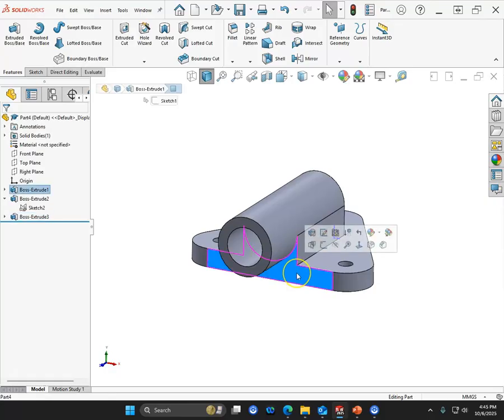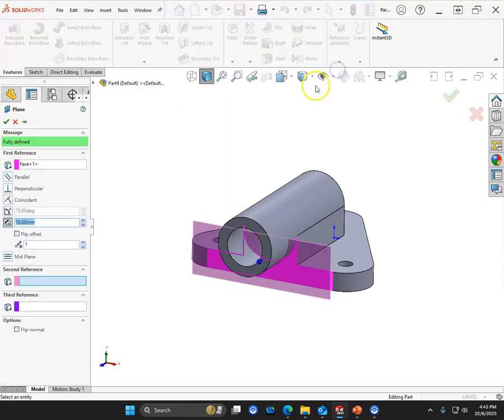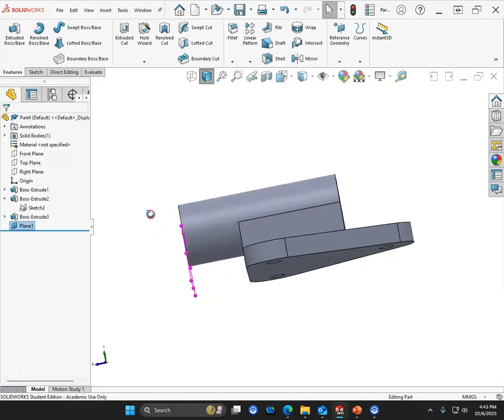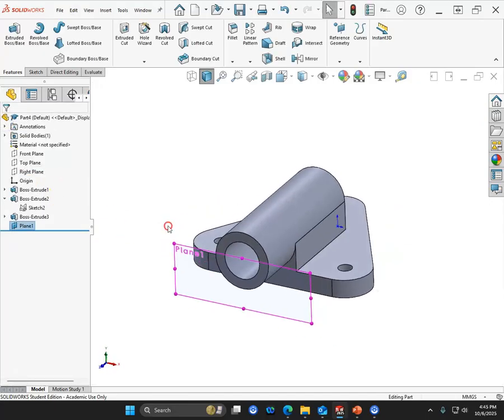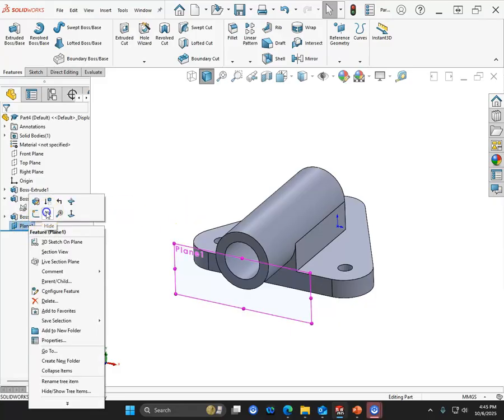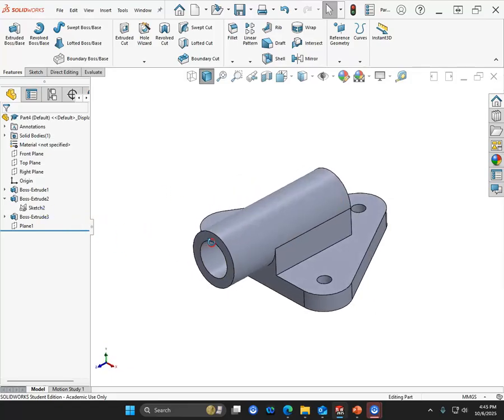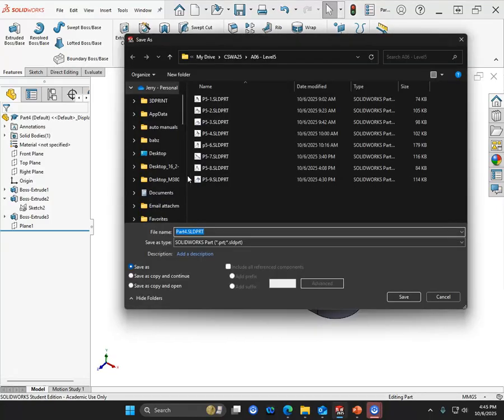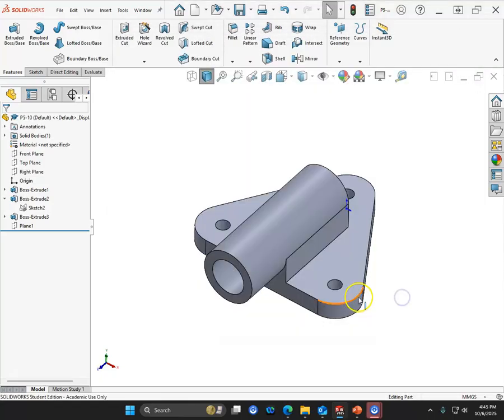just going into that front face, going to the reference geometry plane, we would create an offset plane 30 millimeters and go ahead and hit OK, and that does the same thing as the from and the to. So just keep that in mind, that we may be able to generate that geometry out of the feature, as opposed to having to always create the plane. But certainly the plane would work as well.